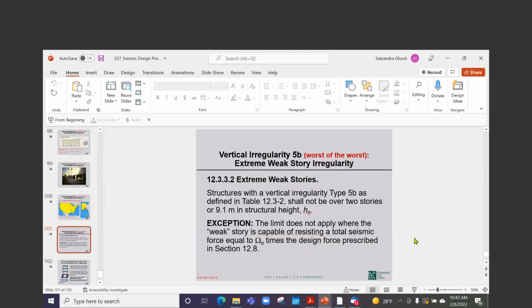So the stiffness will be, if you use the approximate period, the approximate period is shorter than the real period, so you are taking a stiffer building. If you use a rationally computed period, you are assuming a softer building, a building with less stiffness.